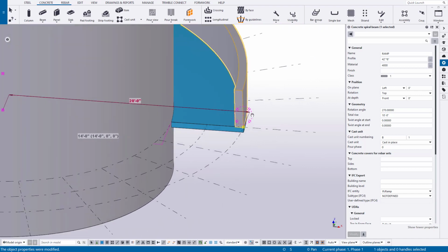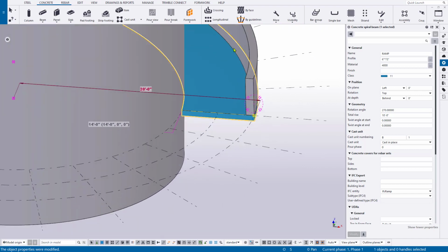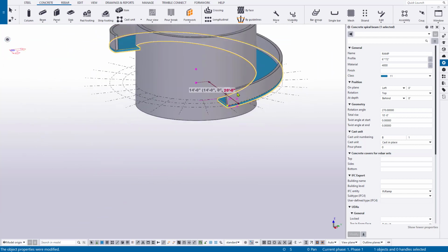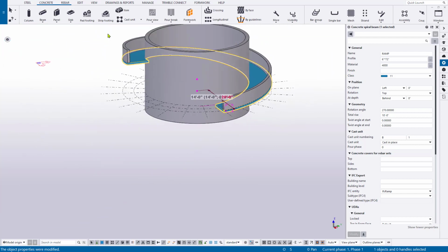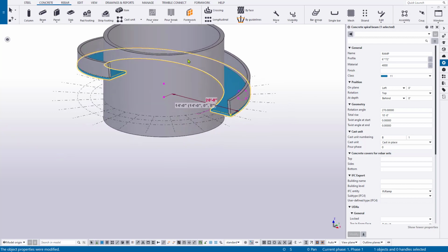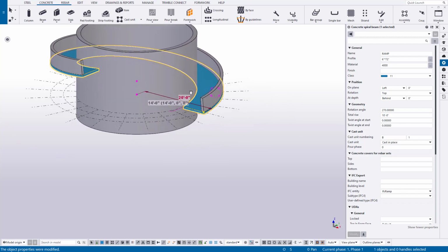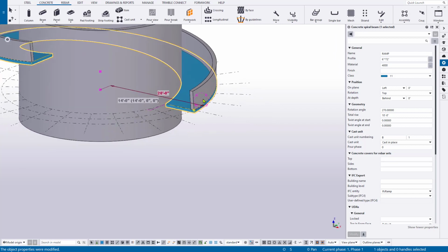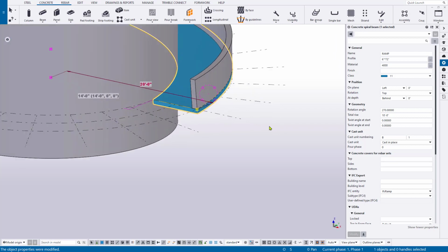One thing too, make sure that you're modeling not only the width of your walk or your drive aisle, but also the thickness that may be required for the wall. Now, if the exterior wall goes all the way down to the ground, you can certainly extend it down that way as well. You may want to use the cylinder and then use a cut plane or cut part, but I would, in this case, just augment the ramp to be slightly wider.